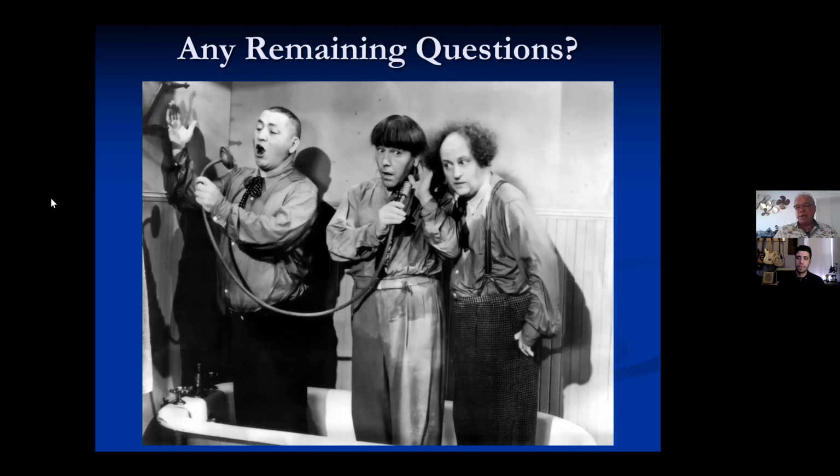So my advice on antennas that have an amplifier attached to them is don't use them unless you absolutely have to. Shure just recently came out with one that does have an active switch. I believe it's +12, +6, 0, and -6 attenuation. If you're going to go with any antenna that has an active amp attached, at least buy one that has a filter as well. Because I've walked into places, people are having these horrible problems, and they have all their antennas on 10 dB, and they're not filtered well. And all I do is pull out the active antenna and put in the exact same log periodic paddle, without the amp, and it cleans up all the problems.